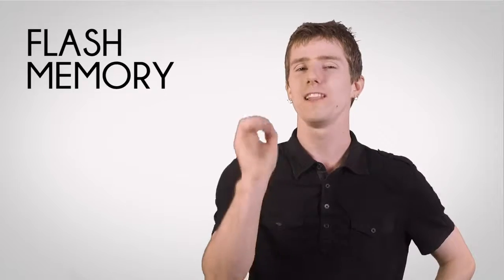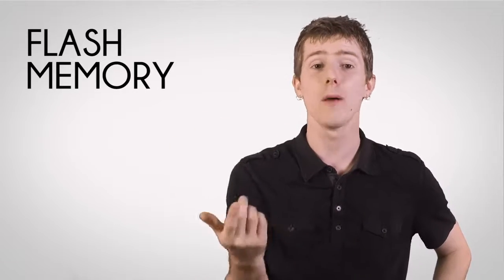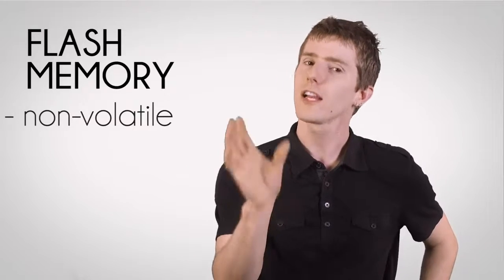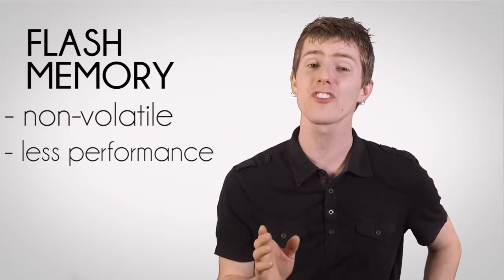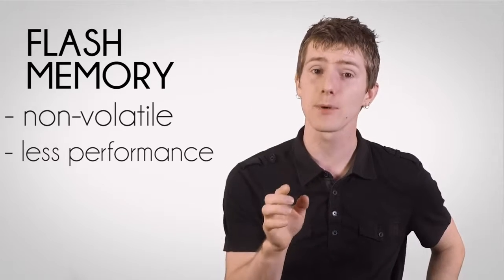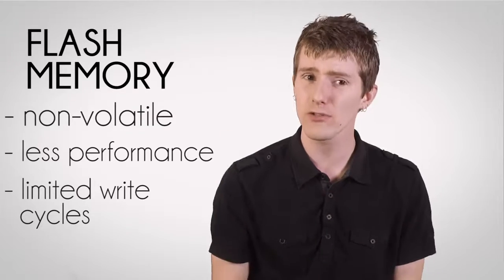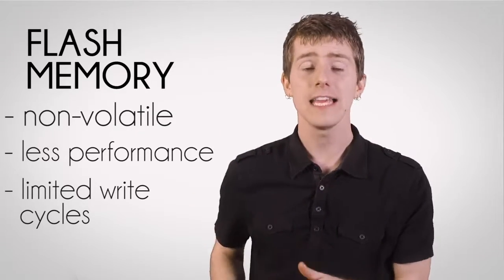Flash memory, which is a subset of EEPROM, is the first type of memory in our rundown that is non-volatile, meaning that data is retained even when there is no power being provided to the chips. This feature comes with a significant performance reduction and a limited number of program erase or write cycles though. This is a necessary trade-off though, because NAND flash is used to store things like the operating system, applications, and other important data that can't be erased whenever the system is powered down in a consumer PC or device.